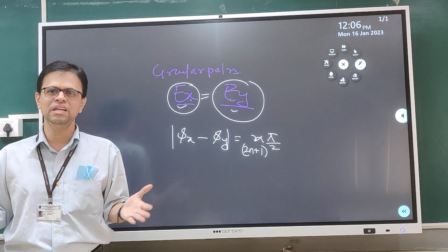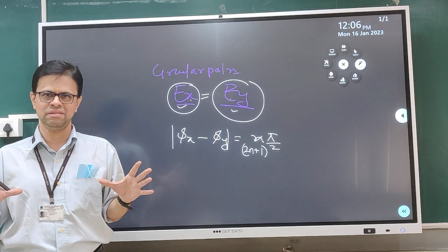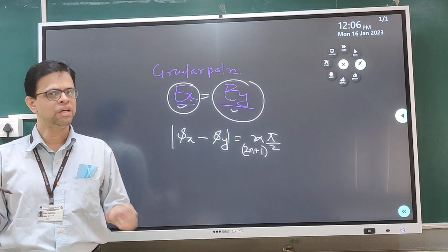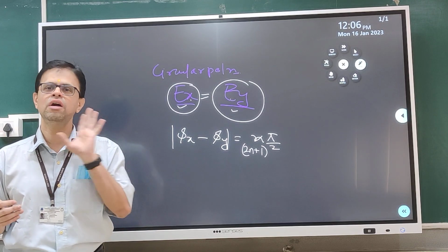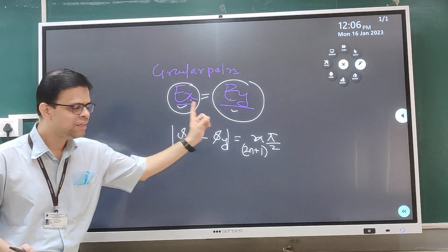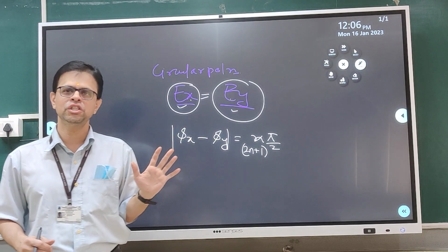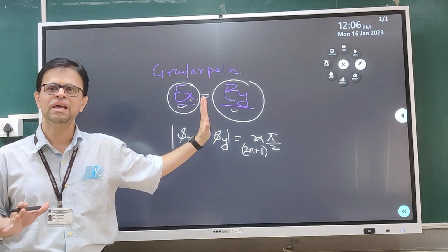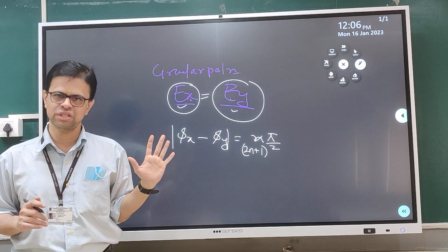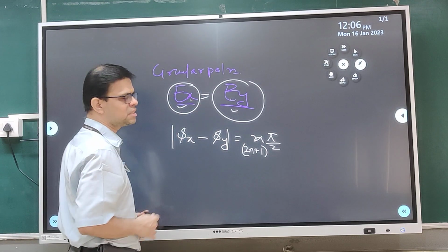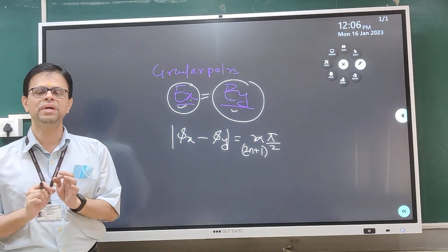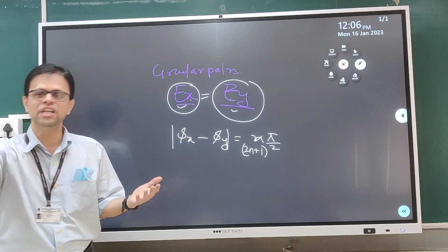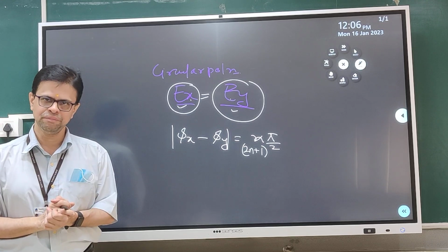Now to realize these three conditions on the antenna is a very difficult task. If you just design a patch and excite it with a given field location, it is not necessary you will get a circular polarization. We need to ensure that these conditions are met on the patch, on the antenna, to yield a CP response. How that is done, we will see later in the various techniques which I will describe. If any deviation from this occurs, then you will obtain an elliptical polarized antenna, or maybe a modification of that will lead to a linear polarized antenna.